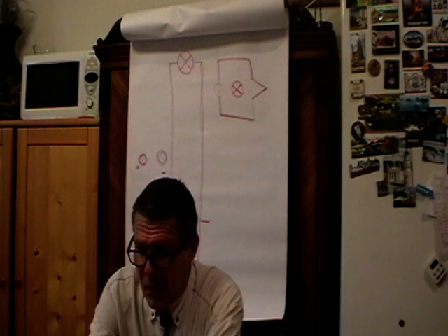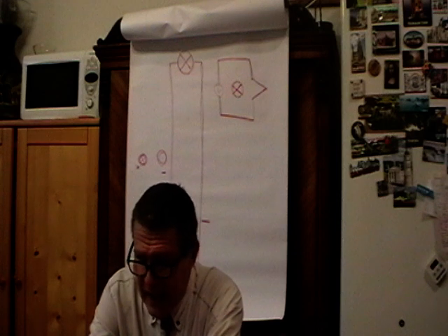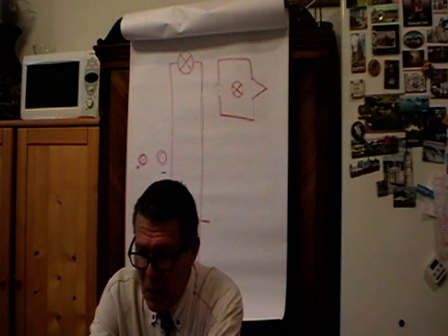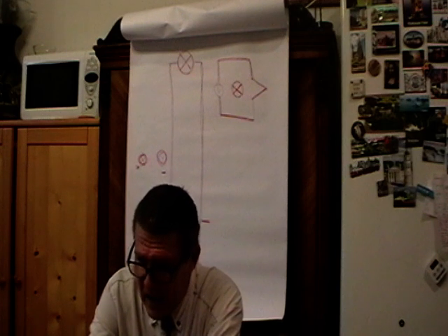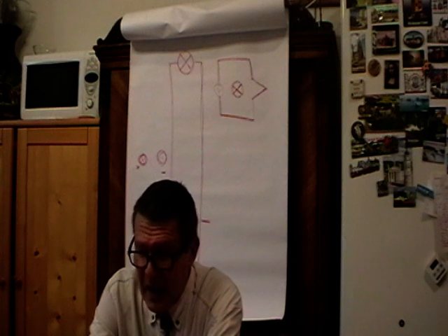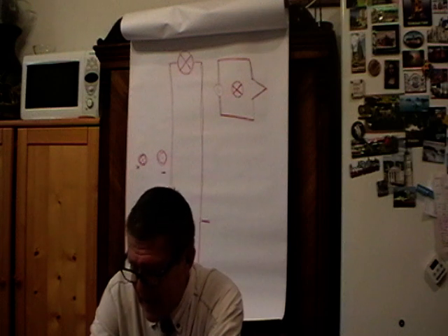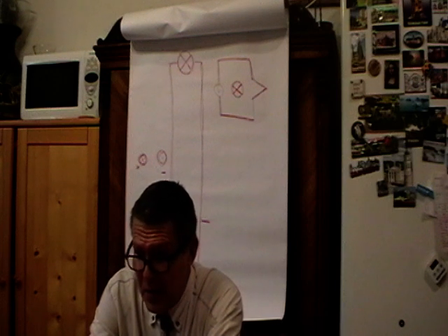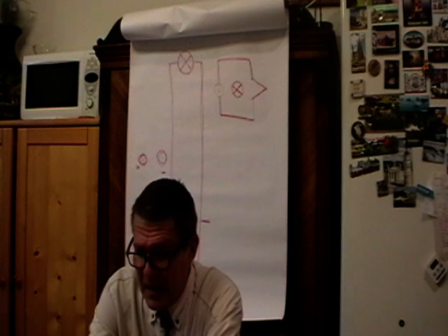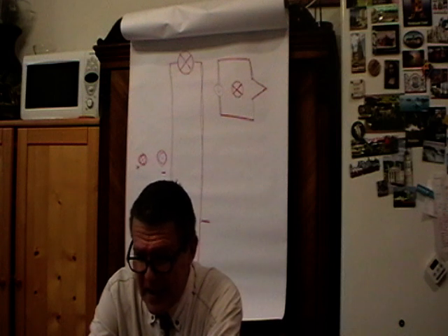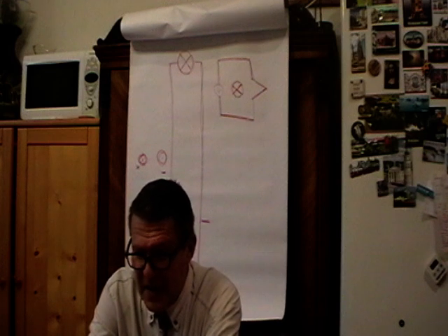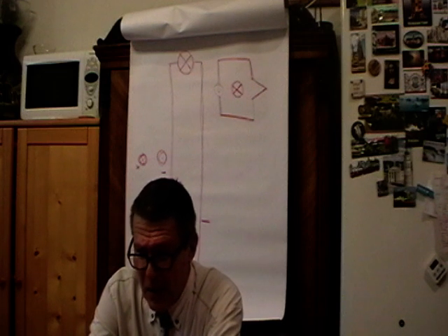So for a metro, from the full velocity, it could take some 300 meters to stop. If it runs downhill, it could be even more. But a tram could stop much faster than a car because it has a special apparatus, which is an electromagnet that really connects it with the rail. And in some cases, it even happened that the rails have been pulled out of ground with this fast slowdown.